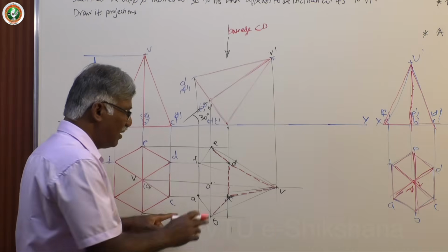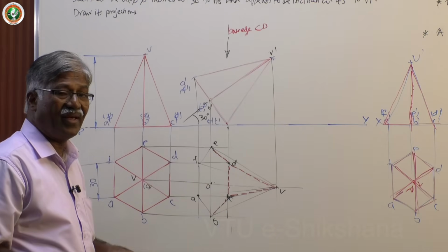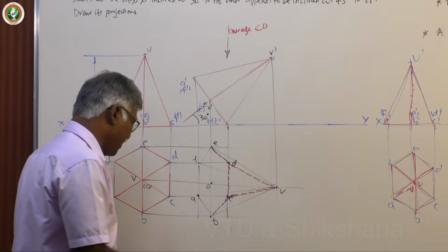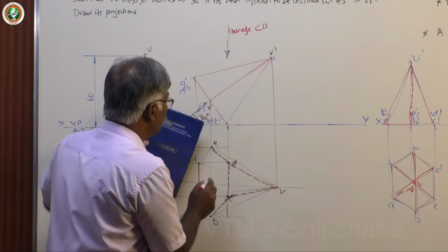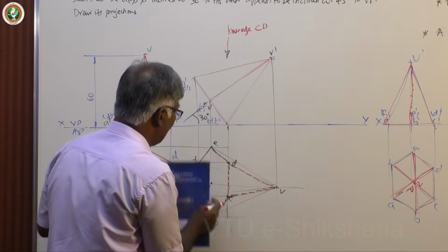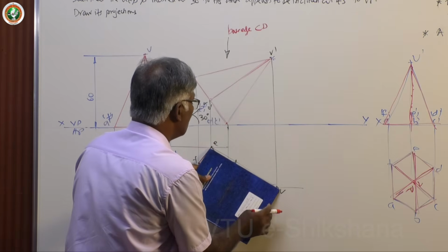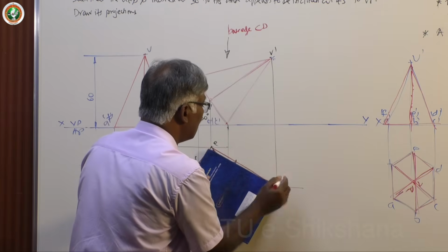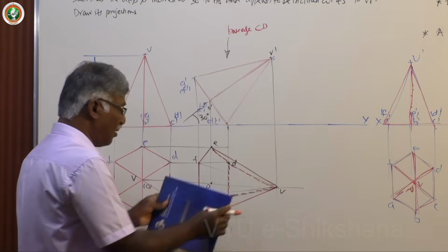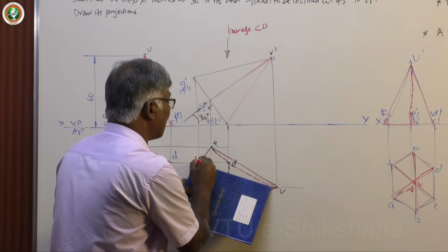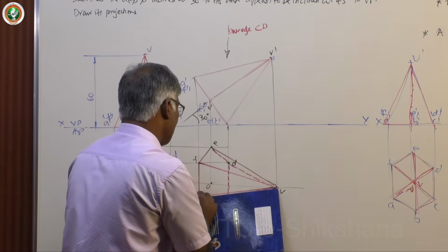These are the invisible lines. All the remaining lines are visible. That's it, a very simple procedure. So dark all the lines. Now as usual, you are going to keep the boundary dark. All boundary lines are dark irrespective of the situation, and all remaining lines are dark. Then you can interpret the same with the key surface method also.